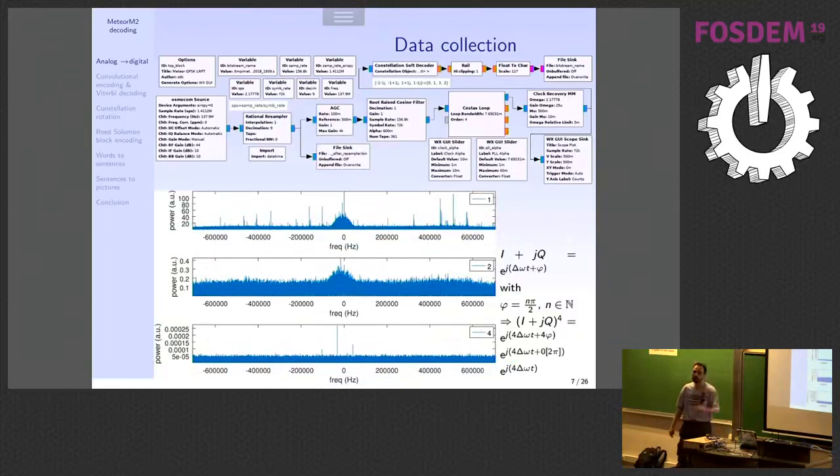Well, if we expand what Paul Boven taught us about GPS, where BPSK is collapsed by squaring the signal, well, of course, if you take the nth power of an NPSK signal, you collapse, again, the spectrum spreading due to the PSK modulation. So here we take our raw signal. Well, there is something, but we don't know if it's the right modulation. We square it. It is not BPSK, so we haven't collapsed the spectrum. We raise it to the 4th power, it is QPSK because the spectrum spreading has collapsed into the carrier. So we can get signals that are worth investigating further. It seems to be QPSK modulation.